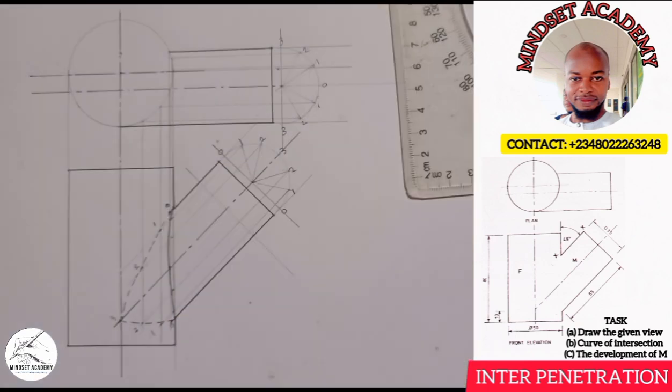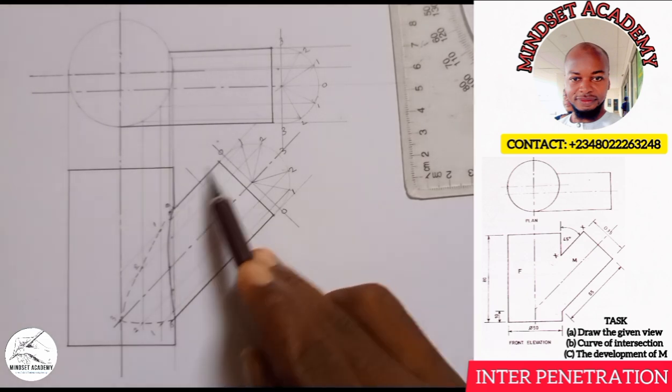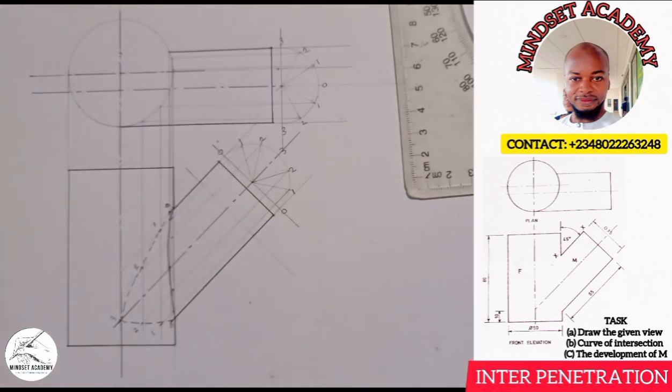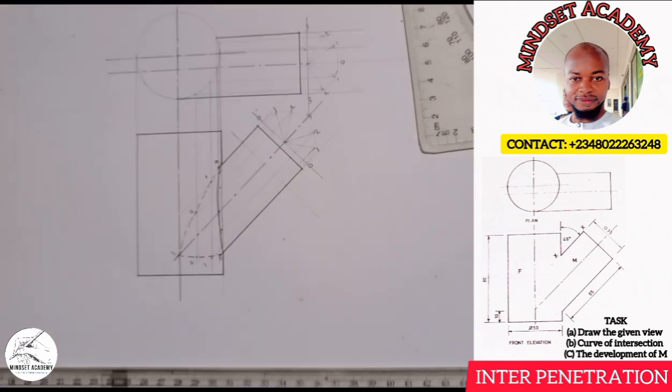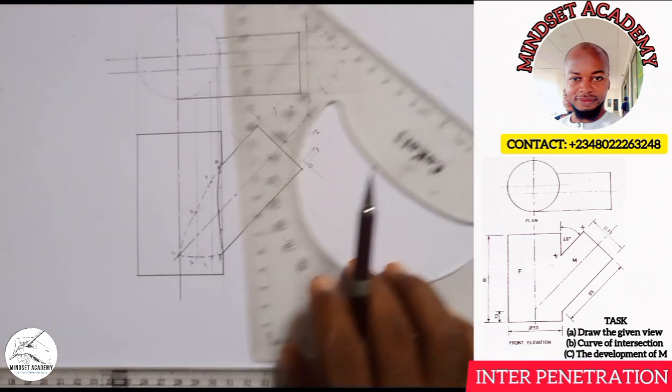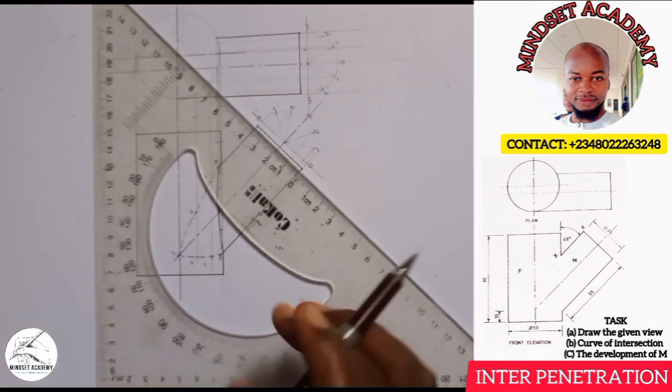Now the next thing that we have to do here is to draw the development of it, right? The development of the part XX as the same. So XX here that the same means this is where we're cutting it open. That is the two sides you're going to expose. So let's do that and see. In doing that, you're going to take your instrument, the same 45 degree, and you project this end here.